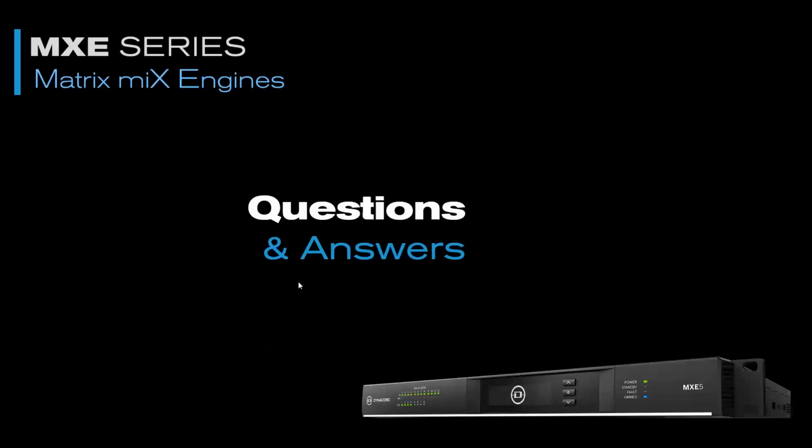I do see a question. This question from Rainier asks, most stadium systems combine PA and VA applications, how about EN54-16 certification? Do you want to answer that one, Christian? Yeah. Our approach here is that the MXE series will work together with EVAC systems, but not be a certified part of it. What does that mean? It means that, for example, an MXE can handle all the background music and all these nice things that you want to do with the system while it's not in EVAC mode.